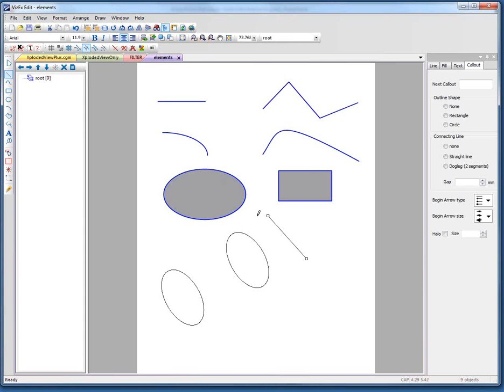Next one I'll show you is snap to midpoint, and it's very similar: the end of a line snaps to the midpoint. Same with segments and rectangles. The third snap-to is snap to nearest, which is common in most graphics packages and probably what you're most familiar with, but now instead of snapping to a specific point, it snaps to anywhere on the object. So you see how it tracks that curve, or that edge, or rectangle, or that ellipse. The last snap-to point is snap to center point, and that applies to ellipses, or if you have an arc which has a center, it'll snap to that.